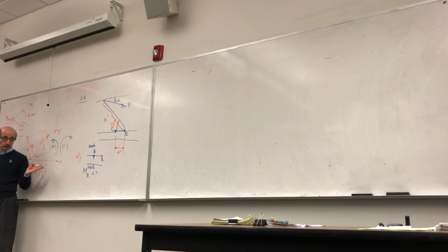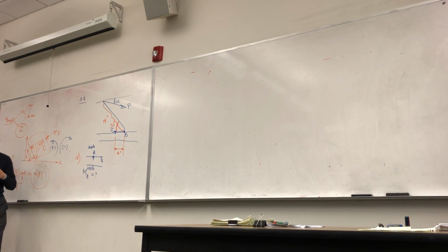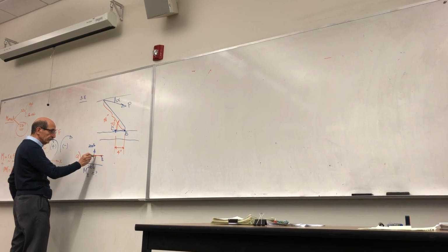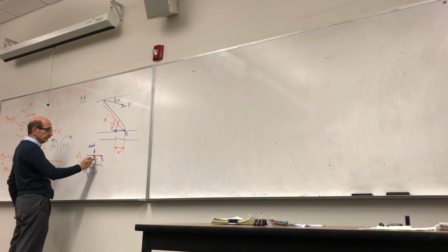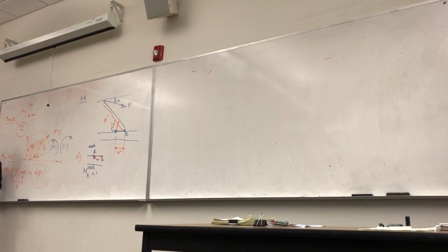Moment of a force in 2D with respect to a point is simply the magnitude times the vertical distance from that point to the line of action of the force. And this is the vertical distance, which has already been given, 4 inches. In 2D, as I said, the only thing that you need to worry about is the direction of the moment.